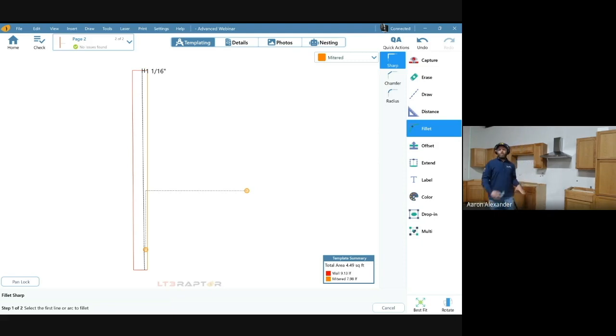Okay, so when you got a long run, you may aim your laser down here and try to hit the bottom of the cabinet down there. The bottom of that upper is what we're going to want to shoot onto. And your laser stretched out like 3 inches because the run's 15 feet down there that you're trying to shoot this point on. That's where we can use this target right here, okay?